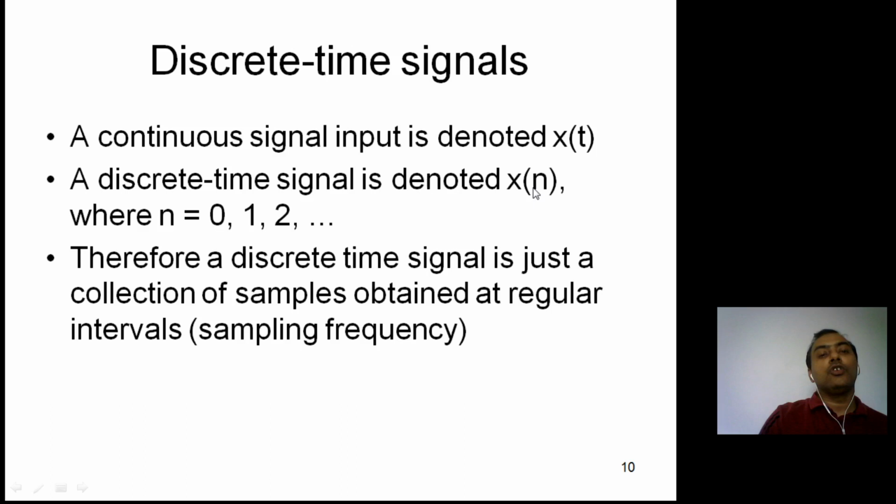Sampling frequency fs is greater than or equal to 2fm. That is the sampling frequency condition, and aliasing: if fs is less than 2fm, then aliasing happens. That means we are not going to get the exact signal. So for that we use the Nyquist criteria, fs equal to the minimum of 2fm. That fm is necessary, and fs is the sampling frequency.